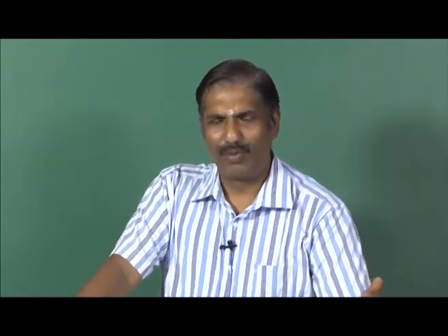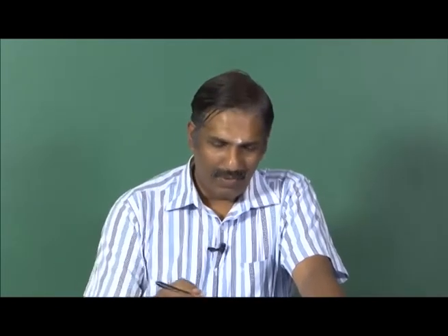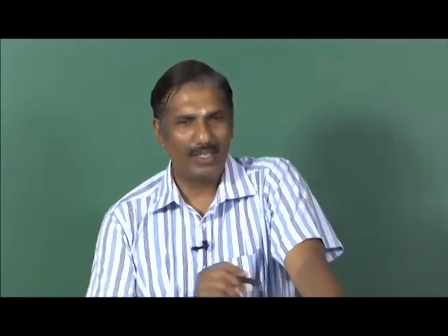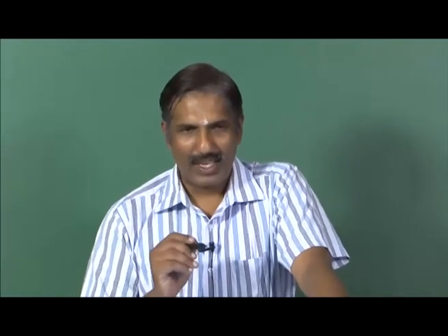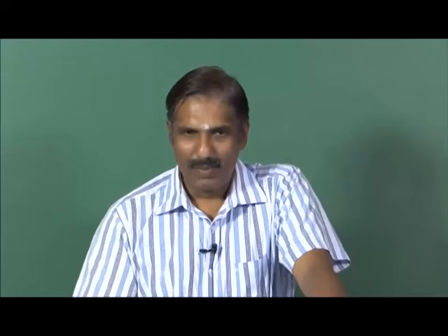Now, about the standards: we said that for a hole the tolerance is 0.002, 0.006. How is this 0.002, 0.006, 0.004 decided? This is decided based upon the process which is involved in generating it. So, now what is happening? We have to set a standard, so that by looking at the tolerance we should be able to understand what process is involved, and what is a standard in one country should also be the same standard in other countries, so that the parts manufactured can directly get into assembly. They need not undergo inspection once again.